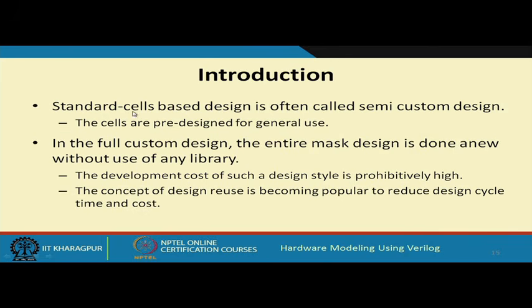So, the standard cell based design which we had seen, this is called semi custom design. Semi because the cells that we are using are pre-designed, but the way we are placing the cells, that is up to us, right. But in the full custom design, theoretically, well, no one will do it this way today, theoretically we are not using any library.